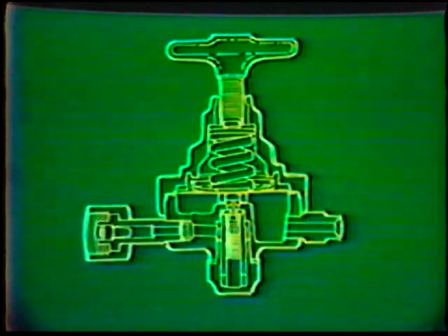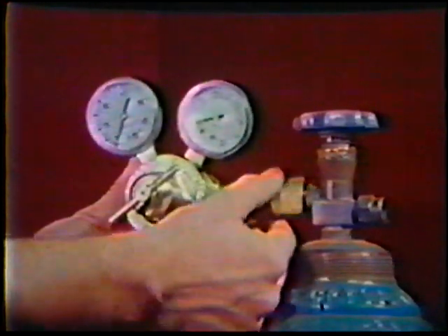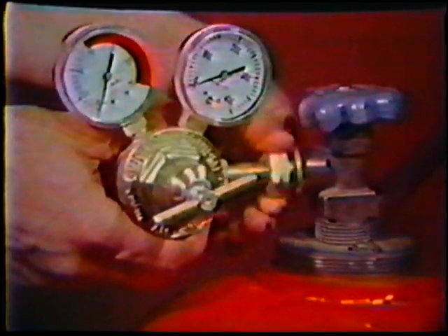The regulators are made up of needle valves, springs, diaphragms, and gauges. Some reduce the pressure in one stage with one diaphragm and are the type recommended for manifold systems. Other regulators do a partial pressure reduction in two stages with two diaphragms. This is the type recommended for use with cylinder supply systems. The regulators for oxygen and acetylene are different and cannot be interchanged. To prevent interchanging, the oxygen connections have right-handed threads, and the acetylene and other fuel gases have left-handed threads.